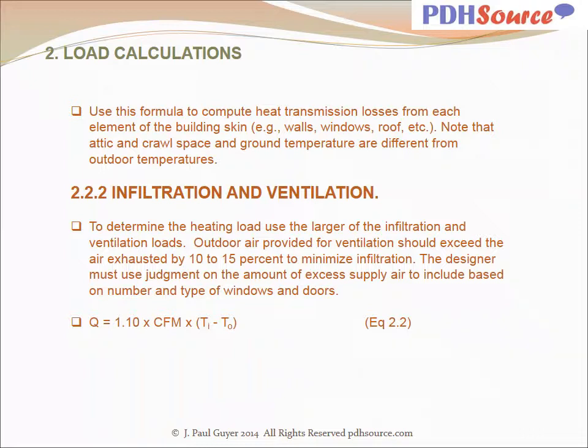The formula for calculating the heating load due to infiltration and ventilation is equation 2.2. Q is equal to 1.10 times CFM times (TI minus TO). 1.10 is just a constant that we won't go into the derivation of. TI is the indoor temperature and TO is the outdoor temperature.